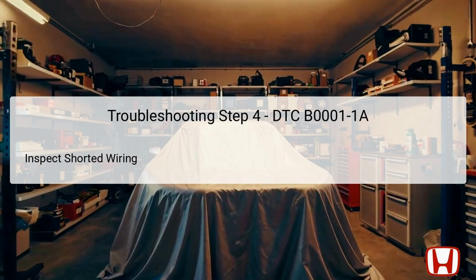The fourth troubleshooting step involves conducting a thorough check for shorted wiring. Before starting this inspection, ensure the relevant connectors, specifically the SRS unit and cable reel connectors, are disconnected to prevent accidental activation of the airbag systems.